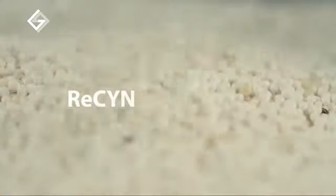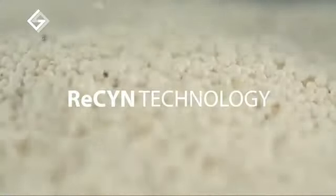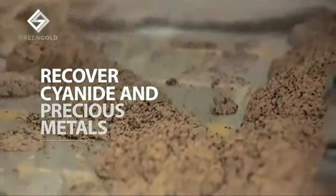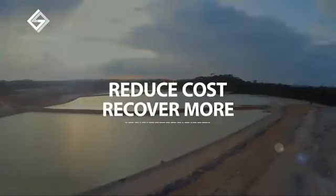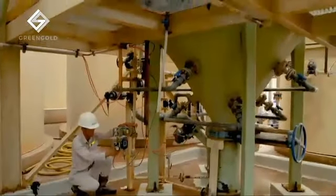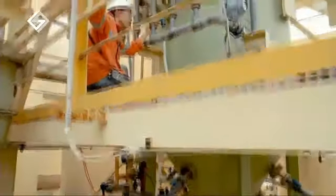Green Gold has a few technologies that we've been able to develop in-house. One of them is resin technology, which effectively uses resin to recover cyanide, copper, gold, silver. Rather than spending money destroying cyanide to detox it, the challenge has been to recover it and recycle it economically. So the technology we have has now overcome that problem.